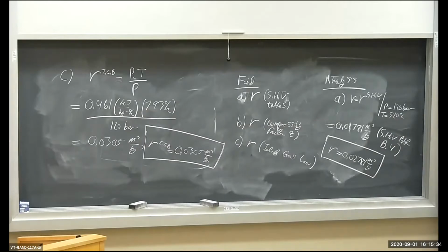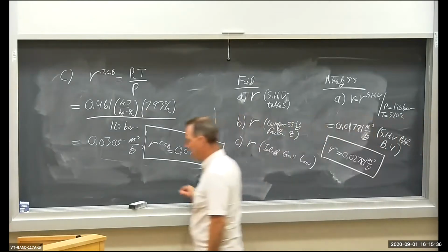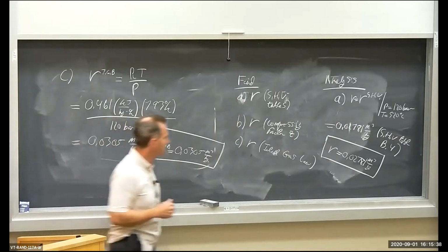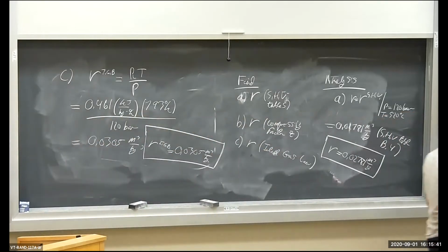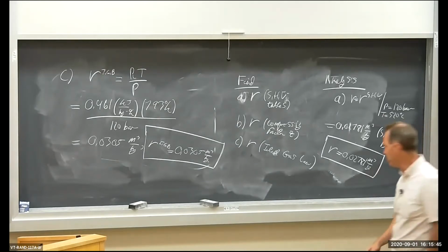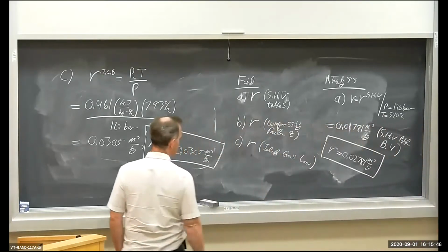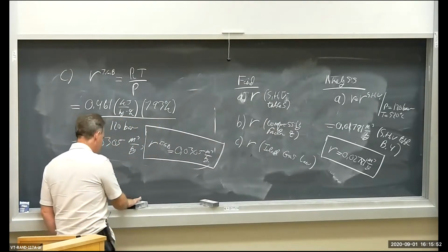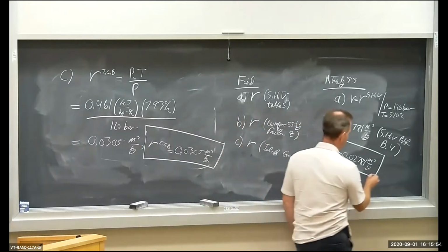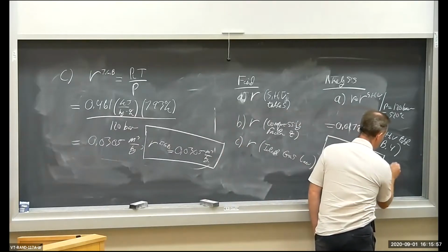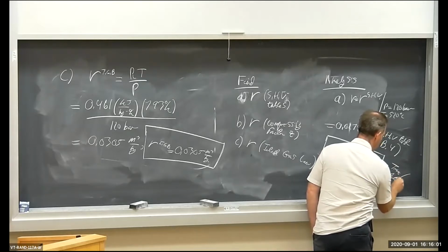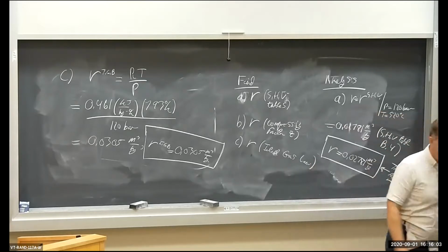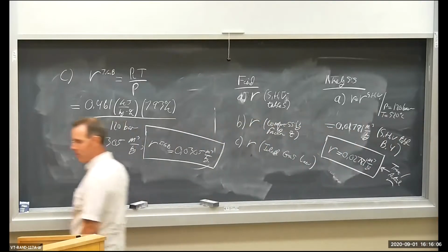Okay, so we have 3 different specific volumes that we calculated in this problem. Part A was using the steam tables, superheated vapor tables. That is our specific volume, 0.27 cubic meters per kilogram. That is the correct, true or actual specific volume. And then we use the compressibility factor.